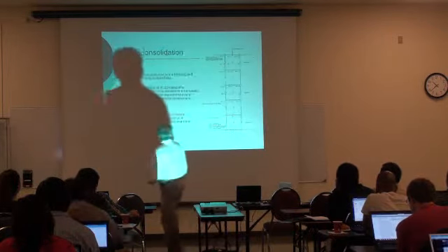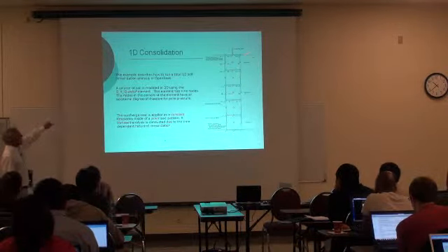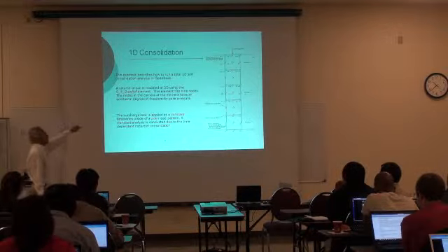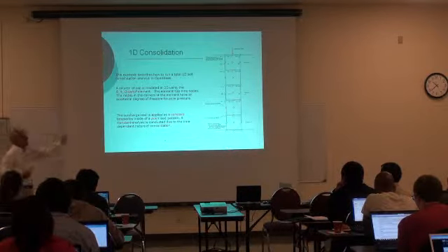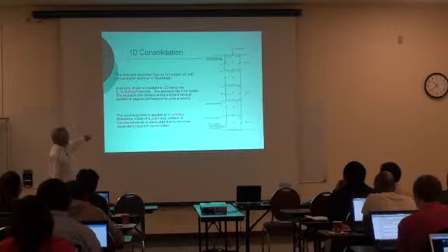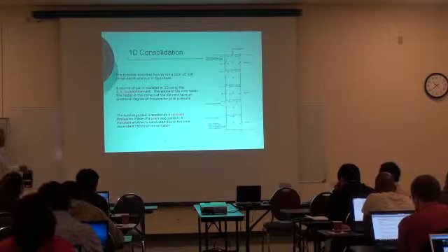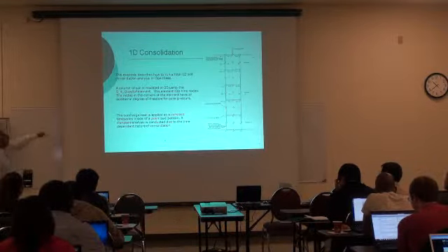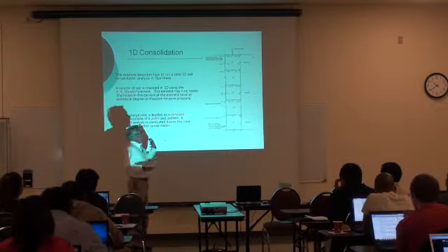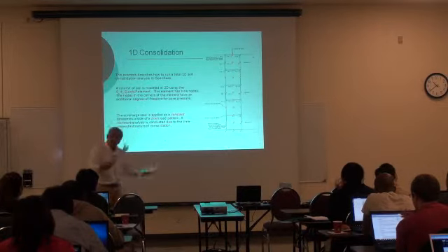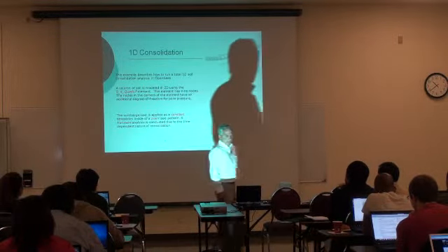The other one is one-dimensional consolidation. Here, what we want to model is the consolidation of a soil column. It could be drained at the top and at the bottom, or single drain only at the top. Here, because we want to model the soil and the water, we use the 9-4 quad UP element. We use a constant time series and a plain load pattern in order to apply a load here. And what you can model is the development and the dissipation of pore water pressures with time. And of course, you can measure the displacements as the consolidation happens.